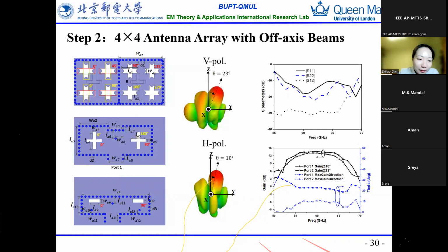Thank you, Dr. Chen. So maybe I can add just a few words. Obviously, when we load it with the dielectric, we'll have dielectric loss, but it won't be equal like a microstrip line. So in fact, you can consider, let's say, two coaxial cables of 50 ohm, but of different diameter. A thicker cable will provide you lower loss.